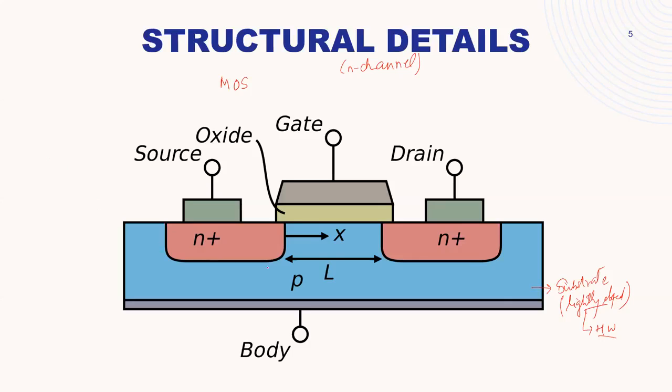So you would be etching out the material from the P substrate and then you will be depositing the N material. So somewhere you can understand the fabrication here itself. Although we'll revisit it, you will create heavily doped regions called N. Then these N regions will start acting like source and drain. So you will start giving the electrical contacts of source and drain to this N region.